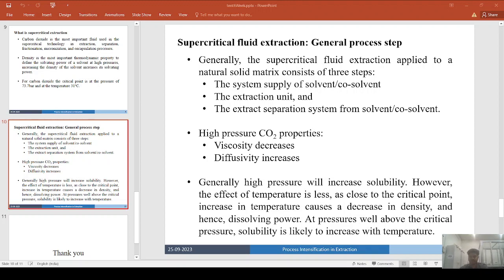So there are some other general strategies to optimize the supercritical extraction. Maximizing diffusion can be achieved by increasing the temperature or swelling the matrix and reducing the particle size. Matrix swelling can sometimes be increased by increasing the pressure of the solvent and by adding modifiers to the solvent. Some polymers and elastomers in particular are swelled dramatically by carbon dioxide, with diffusion being increased by several orders of magnitude in some cases.